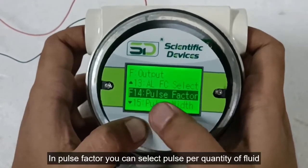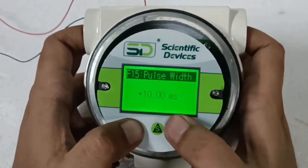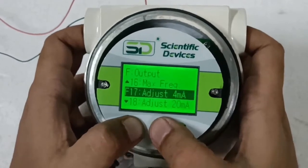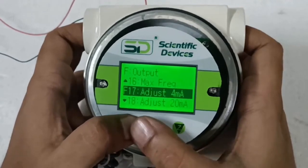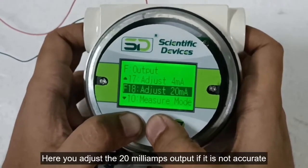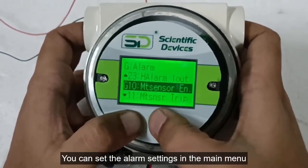In pulse factor you can select pulse per quantity of fluid, and also the pulse width. You can set the maximum frequency if frequency output is selected. Here you adjust the 4 mA output if it is not accurate. Here you adjust the 20 mA output if it is not accurate. You can set the alarm settings in the main menu.